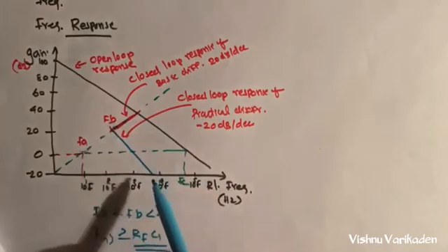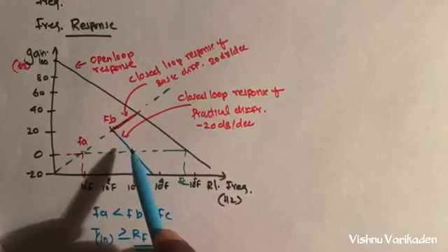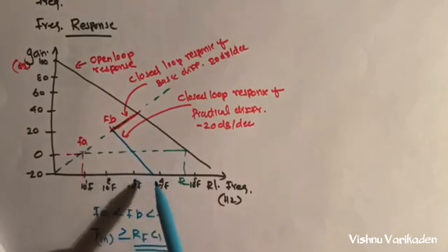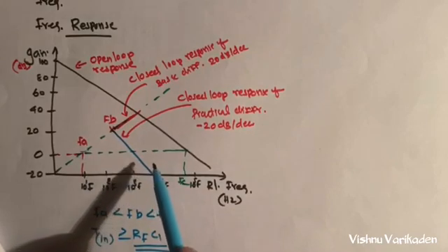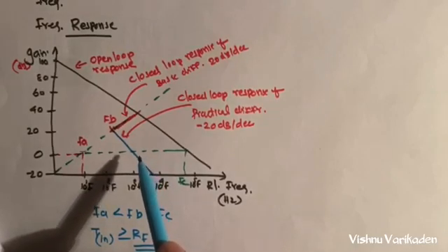That is, we apply the two components. If we further increase the frequency, the gain decreases by minus 20 dB per decade, and the fluctuations or variation in the basic differentiator are overcome by the practical differentiator.